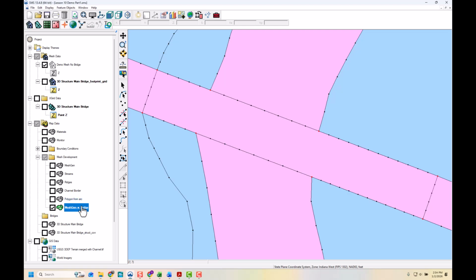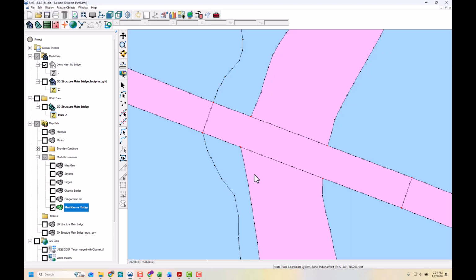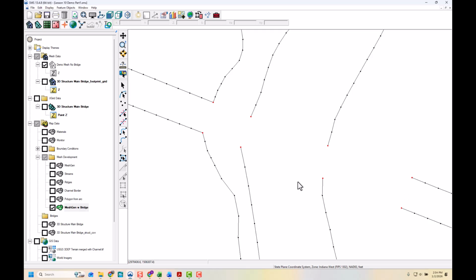And what I typically recommend is, knowing that we're going to have to insert a polygon that is very similar to this one, and in your case it may not be, I still recommend you follow this procedure. Basically, delete any arcs that might be in the way or within that footprint. And so I'm just holding the Shift key. I'm going to delete any of these arcs. All right, so that'll affect the polygons all around.